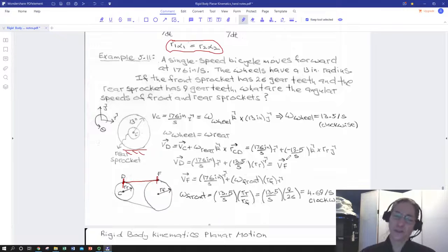So if someone says you've got a wheel that's rolling but it's sliding on the surface, you can't use anything that we did. It's effectively sliding. If it happens to be rotating too, fine, but it's not rolling according to the definition we're using. So just as a caution: if somebody says I have a wheel that's rolling, you might want to ask, is the contact point the same velocity as the surface at all times? And if they say yes, then everything here applied.